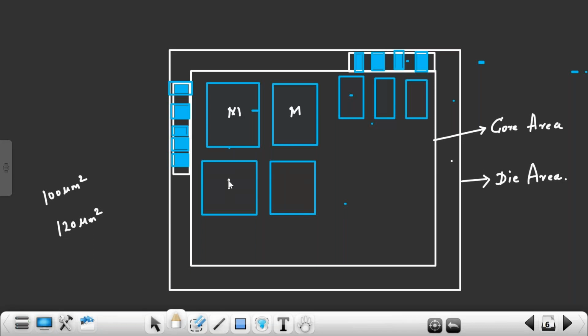So macro placement is not so simple. You have to place a macro in such a way that you are getting enough area for placement of standard cells. So we have to plan how to place the macros. That is called floor plan. Macros will be of small count. If you have 50, 60, 70 standard cells, the macros will be only 50 to 60. All 60 macros, how do we have to place them? You have to plan. That is called macro placement. All these are macros.